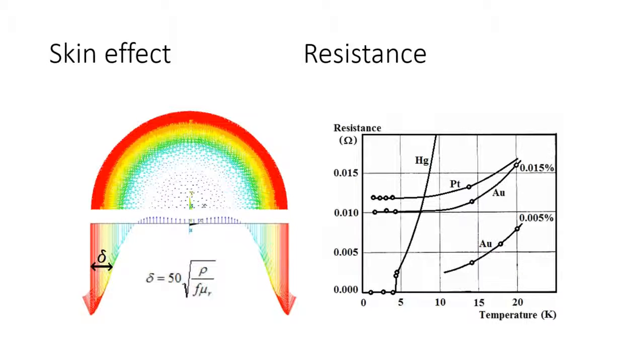But at any rate, before running the simulation, we can usually estimate, for a given frequency, conductivity of material and permeability of the material, this skin depth, and then apply a finer mesh in this zone at which we expect to get most of the current to get higher accuracy of our results.